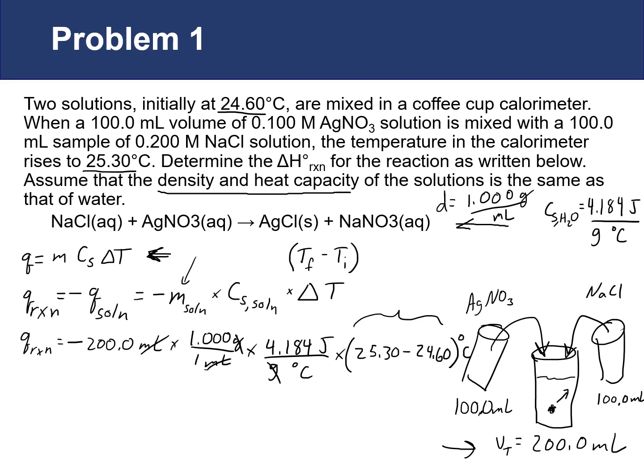The key is to make sure the two temperatures you're working with are both either Kelvin or Celsius. Because we're looking at the change in temperature, it doesn't matter which one you're using. The difference between two values for Celsius is the same as the corresponding difference between the two values for Kelvin. Right, so 1 change in Celsius is equal to 1 change in Kelvin.